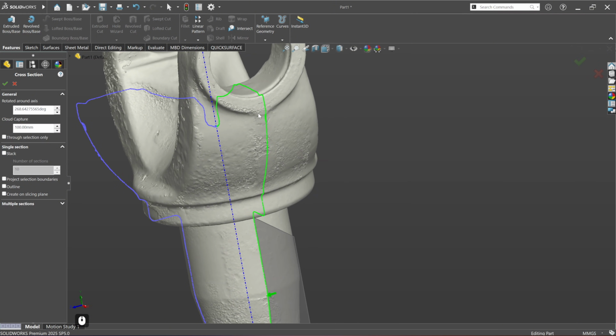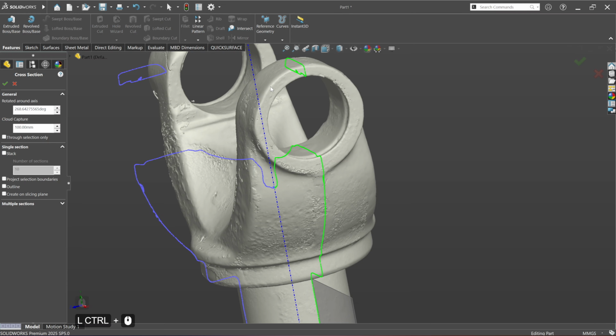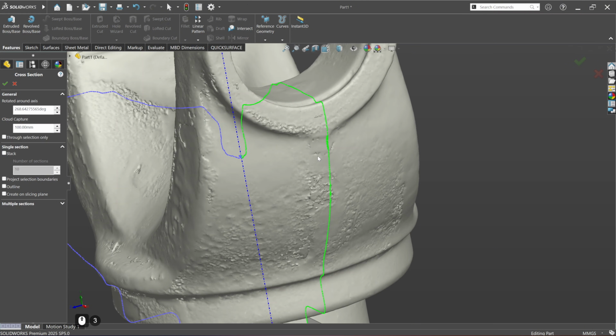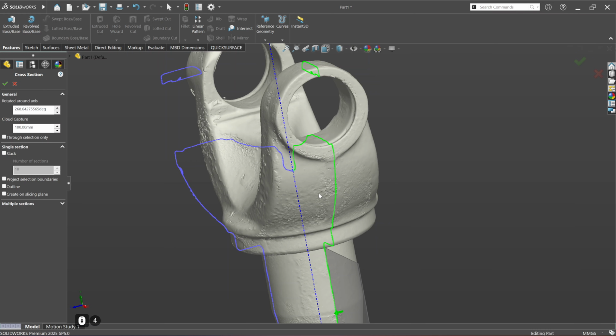Since this is a casting part, it was made from two molds, one from one side, another from the other side, and here we can actually see the split line of the molds. Normally this leaves some unwanted geometry, and we can see in this case it was also there, and later it was just ground away.